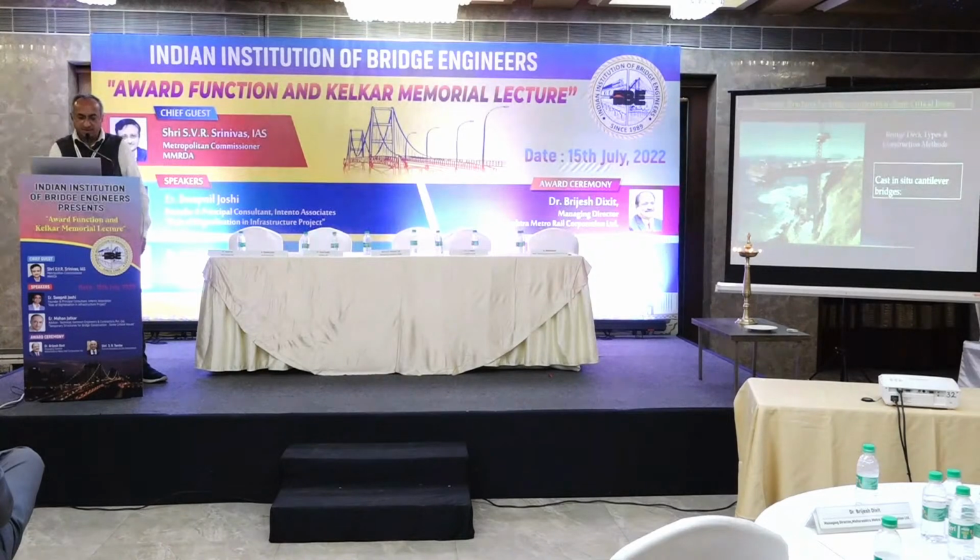This is an example of form travelers which are used for cantilever construction. You can see they are blue colored truss structures which support the formwork for the concrete deck, which is cast in segments of say maybe 3 to 5 meters or even more in some cases.